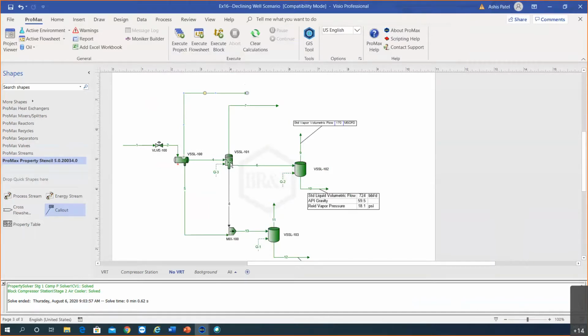Then the next separator is actually a heat treater, or a heater treater. So we have some desired outlet temperature as well as a desired pressure. And we're going to be separating vapors off the heater treater as well, some hydrocarbon liquids, and water if there is any extra carried over in our original hydrocarbon liquid stream. And then finally, our hydrocarbon liquid stream gets to an atmospheric hydrocarbon tank where it would be stored.